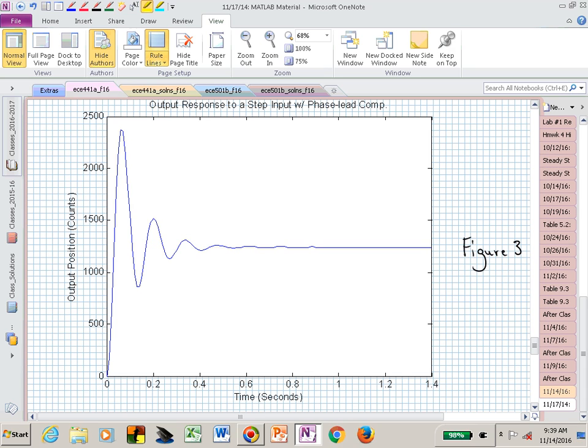And in that case, you may just want a phase lead controller without a pure integrator. The question was, if you only enter a derivative term, will it dramatically change or increase your steady state error? Probably it will deteriorate your steady state error, but it really does depend on the system.